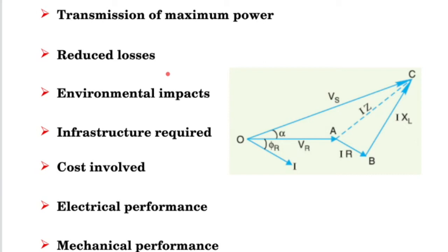the resistance of the conductor. Now, we cannot do anything with the current I, because that is the current that we want the conductor to carry and take to the consumer premises for their various equipment or appliances connected to it. And we cannot do much with the resistance R as well, because R will always be there. We cannot minimize it too much. R is rho L over A, where rho is the resistivity of the conductor material. L is the length.